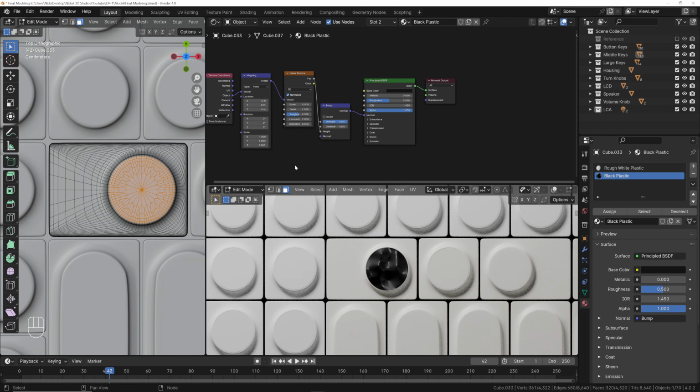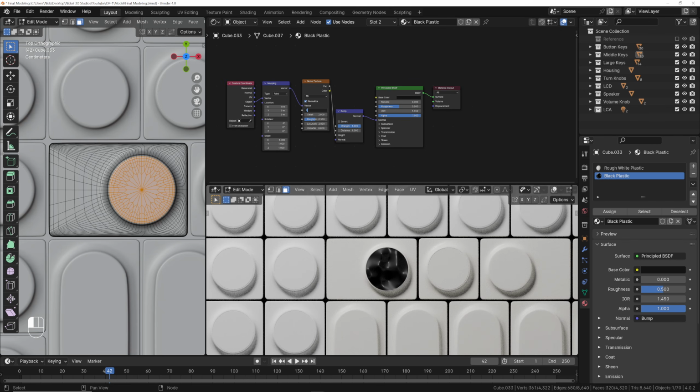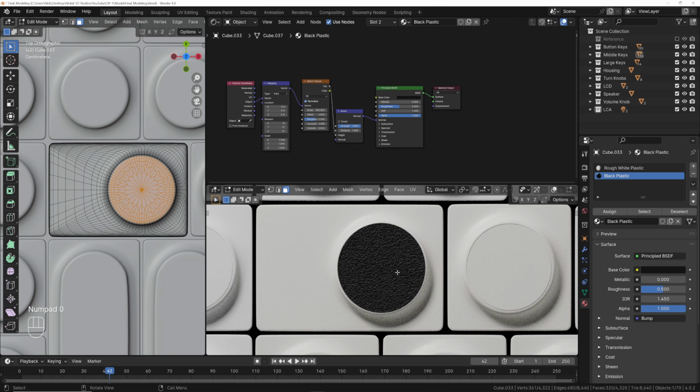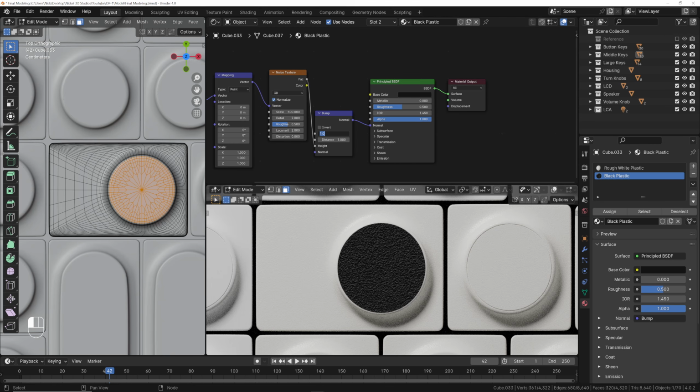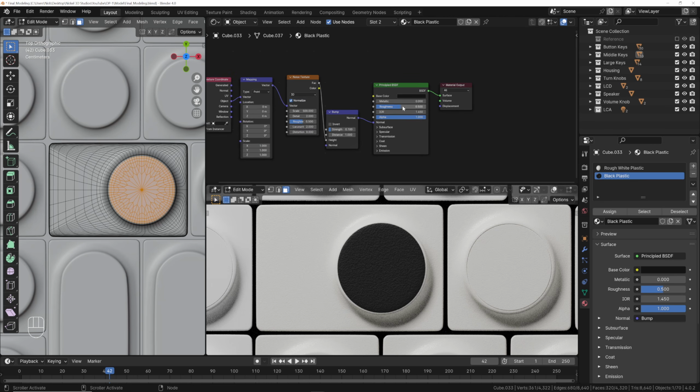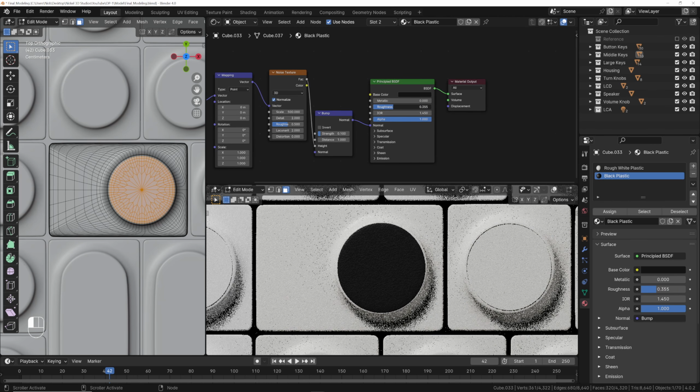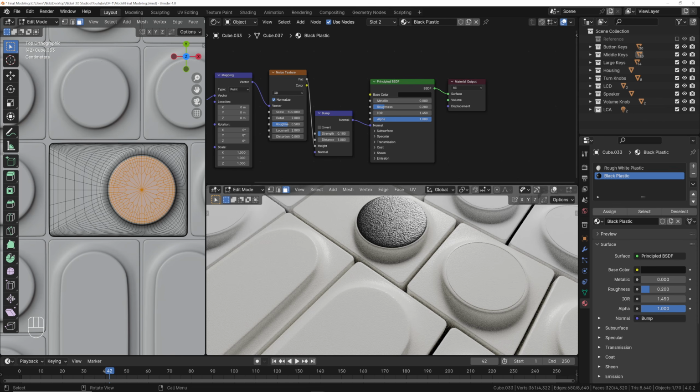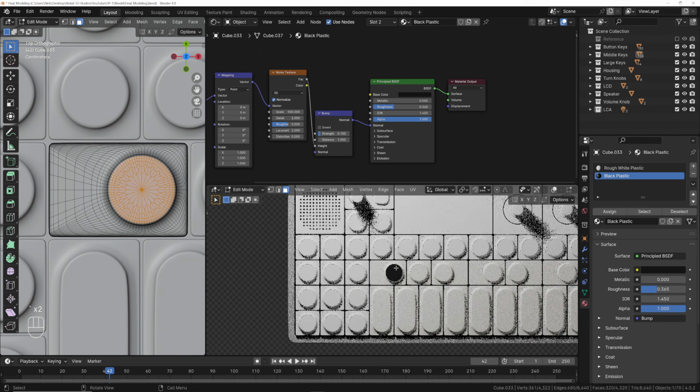It's getting very weird results because of this scale. So let's set this to something like 500. Just to give it some nice texture, we're going to drop this down to 0.1 or so. And then the roughness, you can play around with this. I like having this probably around 0.2. That's going to be where if you look, you get some highlight. You can have a little bit of stuff there, but you might want to have it something kind of like that. 0.365 is what I have that set on right now.